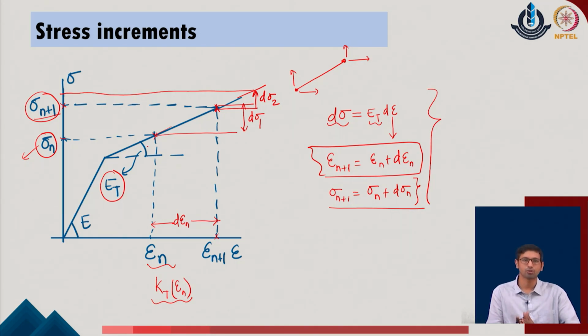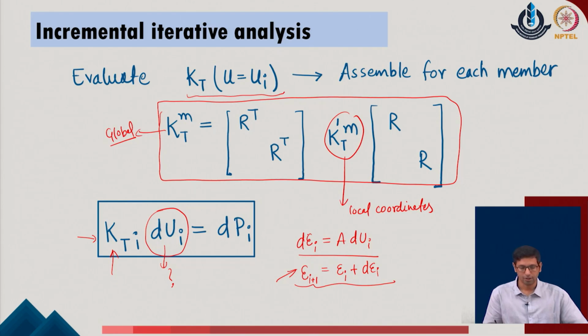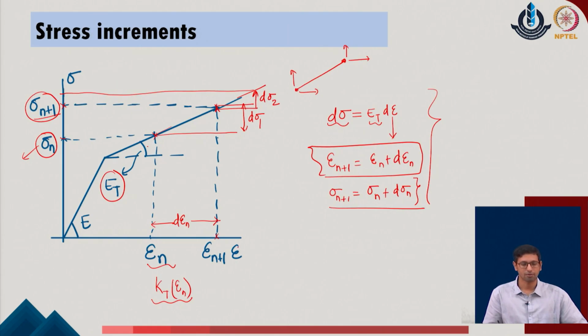So, we are already trying to write something which was earlier done with respect to the load increment, but we must realize that any part of the load increment, as we already showed here, is also trying to generate the amount of the strain changes in the given system, and this strain change can be associated with the amount of the stress increment in the given system. So, what we are trying to define now, that to track the material relationship, the stress increment which is identified in the given system is being referenced, and corresponding to that we are trying to see whether the corresponding stress increment which is being provided will require any kind of corrections, or the user can simply go ahead with the answers which are being obtained by the simple algorithms.